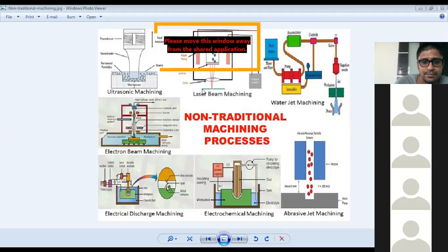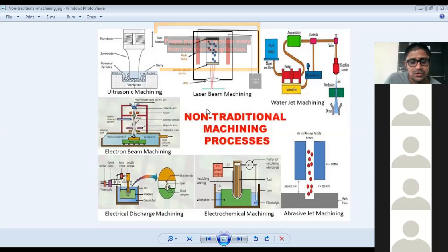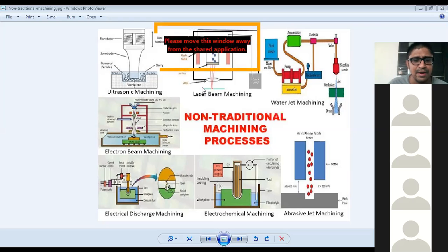Okay, but sir, in laser there is one problem of absorptivity. Is there any difficulty in machining copper and aluminum? Obviously, yes. Absorptivity means what? Laser works on the principle of absorption and reflection. Let us take an example: the laser we use for marking on a wall, the 50 rupees laser, that is more about reflectivity.